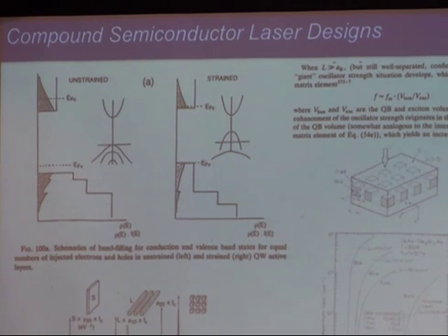So it's mismatched. What was proposed is called a strain quantum well laser, by applying strain in the quantum well, growing it on lattice mismatched substrates. I think we know if you choose different lattice constants, you can strain the material, and when you apply strain, you can rearrange the valence bands. You can push up some bands and push down some other bands. And when you push up, typically the light hole or the split off to the top, that becomes very similar to the conduction band. It becomes very symmetric. And then that lowers the threshold injection. I think you can pretty clearly see now why it will lower it. With much lower hole density, you can start pushing the Fermi level into the valence band now. Does that make sense? And achieve the inversion condition.